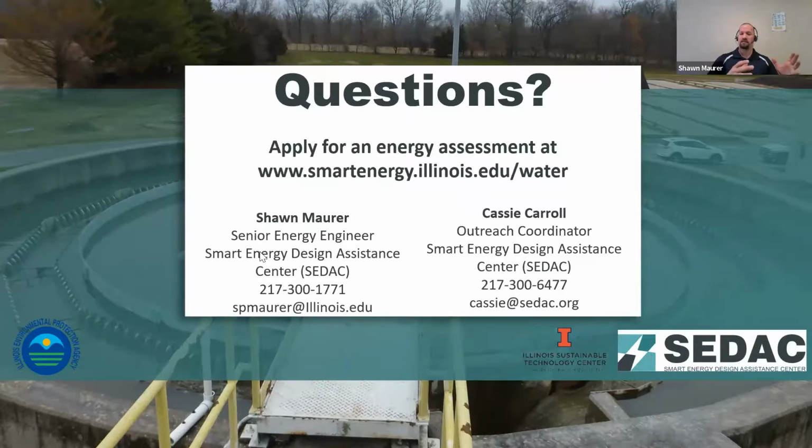And so that specific energy will change over time. Generally, the more you slow down the pump, in most design conditions where that design point of operation is slightly to the left of the best efficiency point, your specific energy tends to increase over time. When you have that slightly to the right of the best efficiency point as a design option, you see a slight decrease in specific energy, so you reduce your total energy demand, and then it will start to increase again as you get lower in speed. And usually that's where you want to program into the VFD a cutoff, so you're not increasing your energy consumption again.